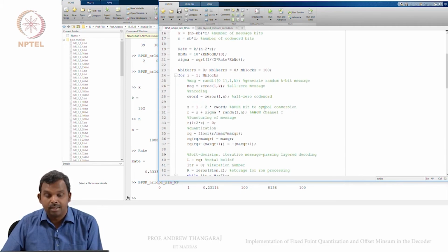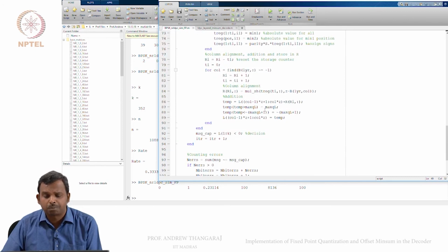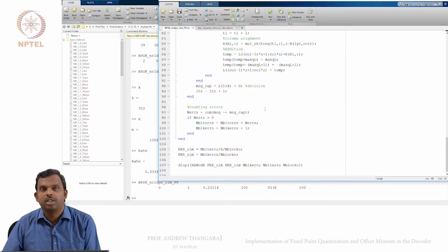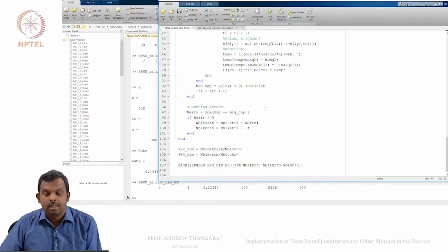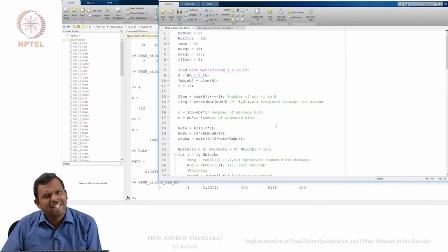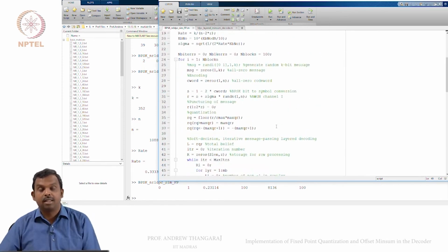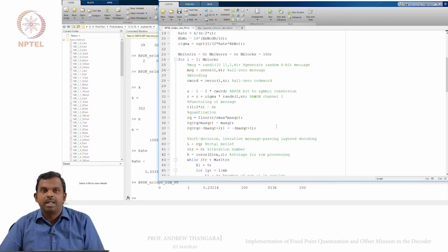Okay, so that's the end of this lecture on LDPC codes, and with this we come to the end of the LDPC codes part of this course. So like I promised at the beginning of the course, you have an encoder for a code in the 5G standard, and you have a decoder also, sort of a working decoder. I'm sure it can be made better. There are lots of bells and whistles you can add, but it's a pretty good decoder. It's got quantized received values, it's running offset Min-sum, and you can play around with these parameters to see how you can change and improve, etc. And some of this we will leave as exercises for you.